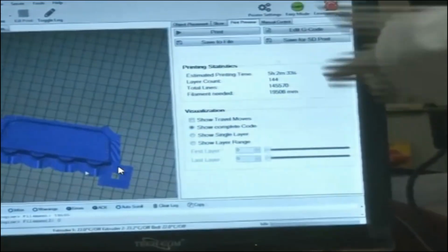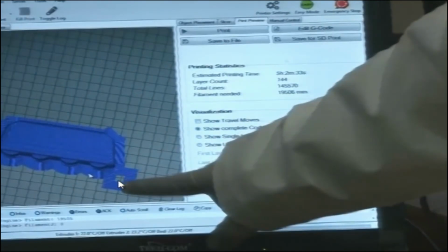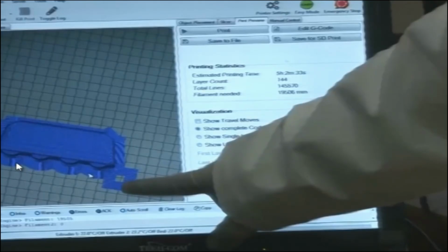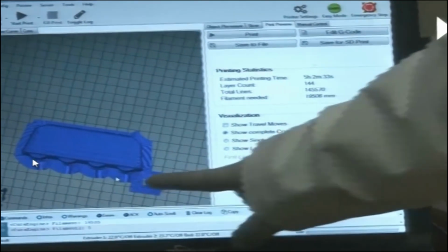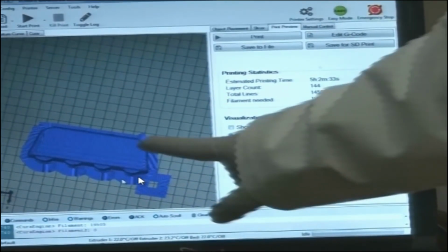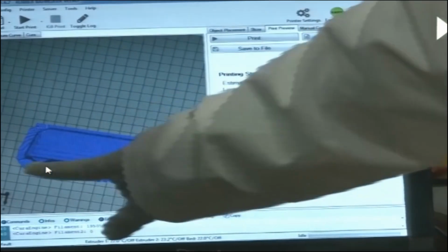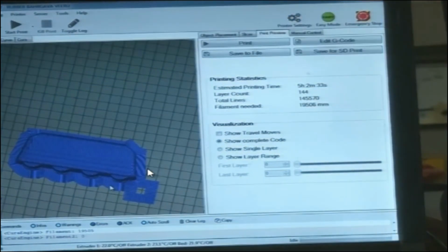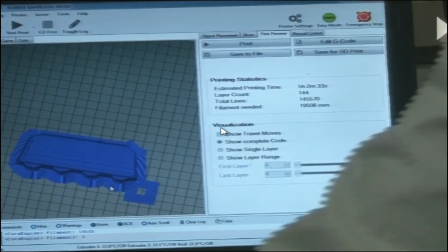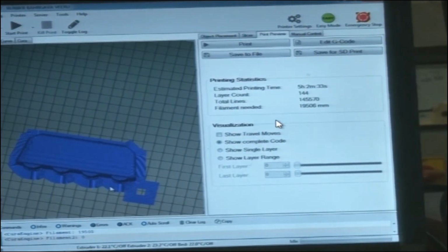So this brim, you can see this square is there. Why is this square there? The square is for holding. We need to hold the job and take it off. Hold the brim layer and take it off. This square is for holding, and the other portion, this outer portion, is the brim. It would like to save the edges or make the edges proper. Brim is only at the edges. Had it been rough, it would be along the complete surface of the job. So this is slicing.